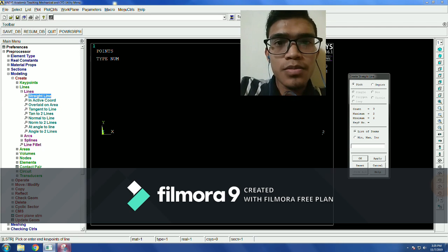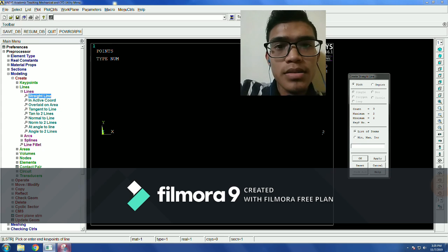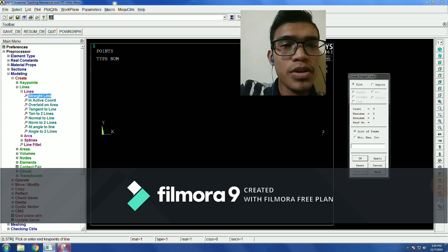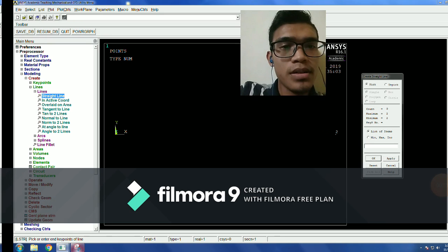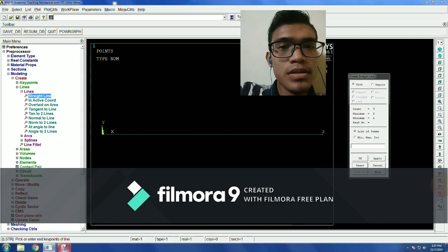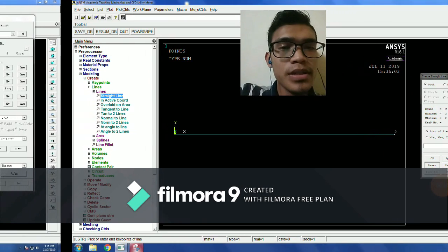First, we go to preprocessors and go to modeling, create and choose lines, and click lines again and choose straight line, and 2 point will appear on the screen, and we click at that 2 point and a straight line will appear.